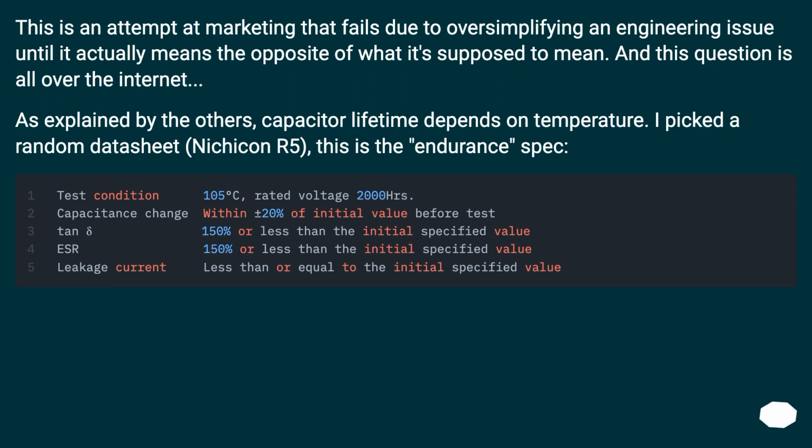This is an attempt at marketing that fails due to oversimplifying an engineering issue until it actually means the opposite of what it's supposed to mean. And this question is all over the internet. As explained by the others, capacitor lifetime depends on temperature. I picked a random datasheet, Nichicon, this is the endurance spec.